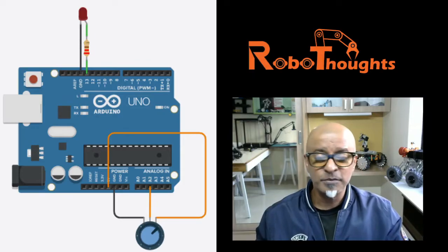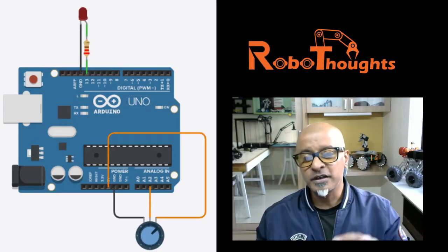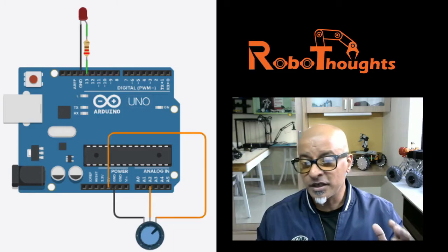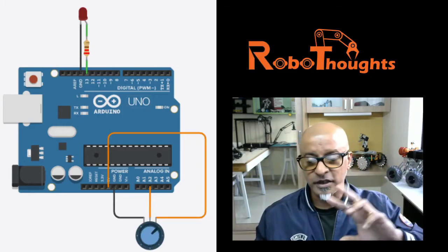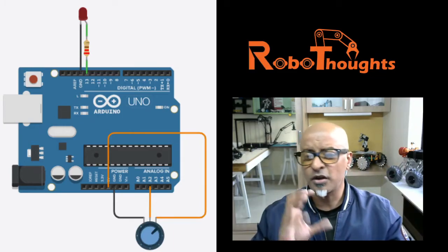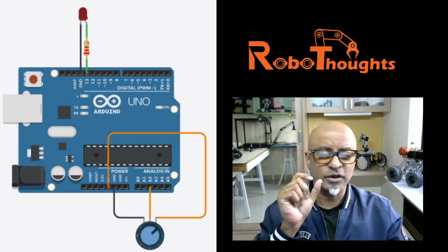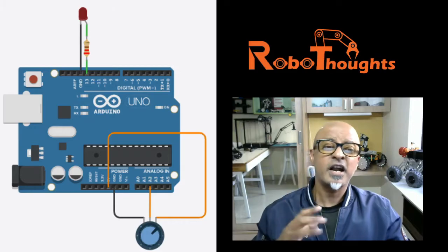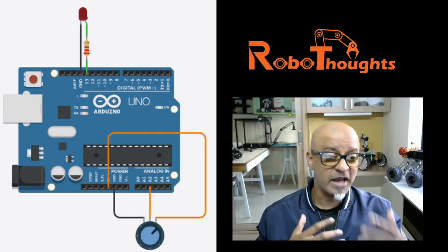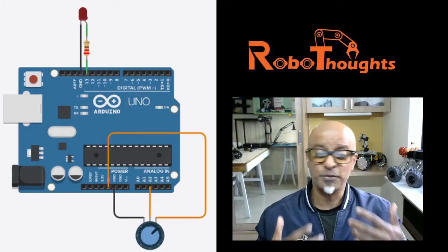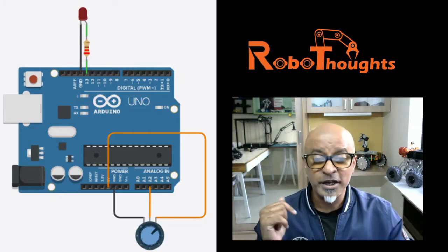We read input 0 when the shaft is turned in one direction, while we read input 1023 when the shaft is turned to the other direction. That is how the logic works. In between, turning the input between 0 to 1023, we get the desired value returned by the analog read function. It is proportional to the voltage being applied to the pin.